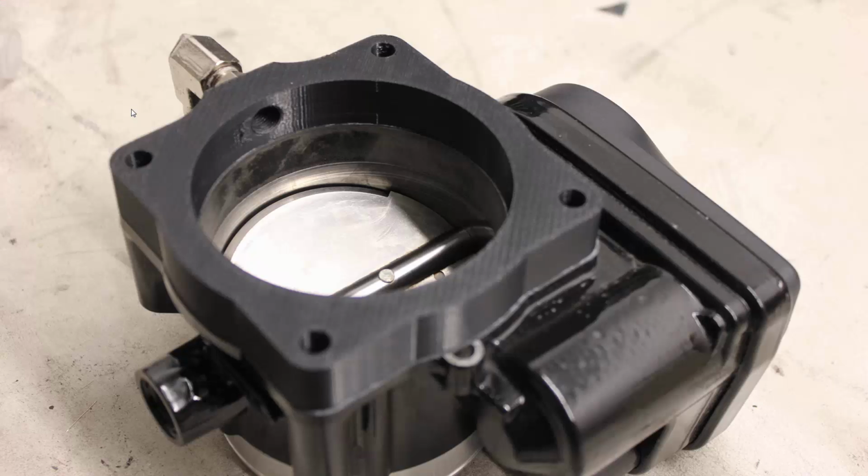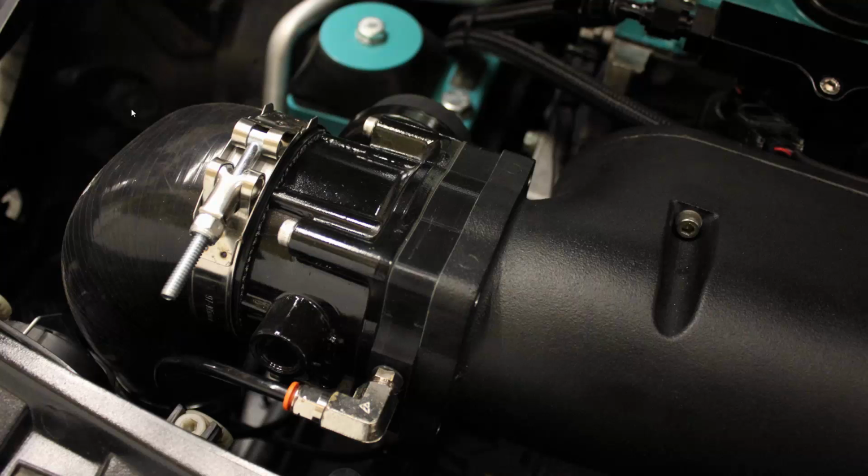And here it is installed on the car. So hopefully it's not too confusing the order I'm presenting this info. I see how it could be if you weren't 100% familiar with the setup of the car or exactly what the throttle body looks like or the intake manifold or whatnot. But what you're looking at here on the far left, you have a silicone connector that's coming up from the intercooler. The air is going to hit this throttle body. The throttle body is going to let a selective amount of air in depending on the idle or the amount of gas pedal I'm applying. We have this spacer where it's going to be injecting some water methanol, and it enters the engine at that point.